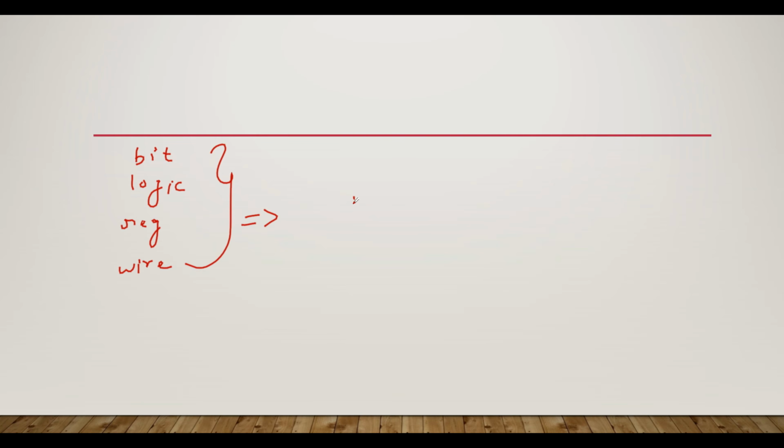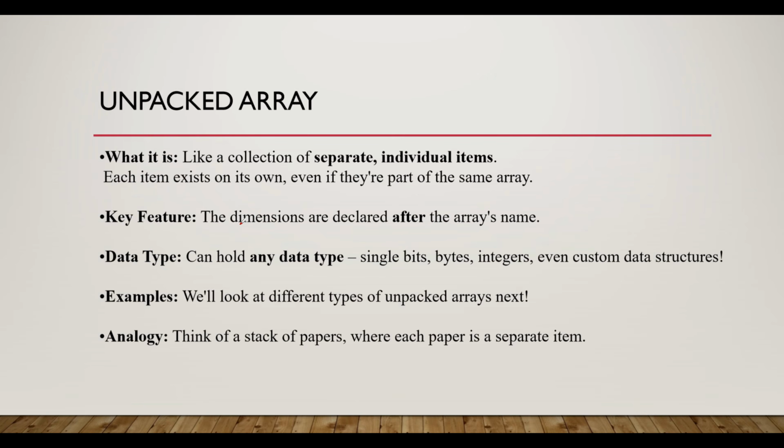You are not allowed to use int and real. So these data types are not allowed in a packed array. Keep this in mind: while writing a packed array, you have to use only single-bit data types. Okay, now let's see the unpacked array.